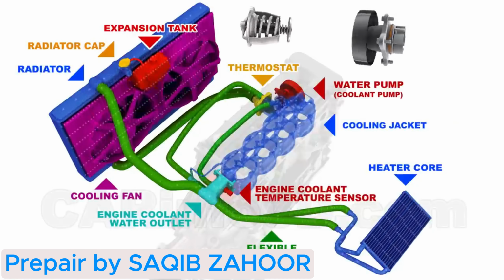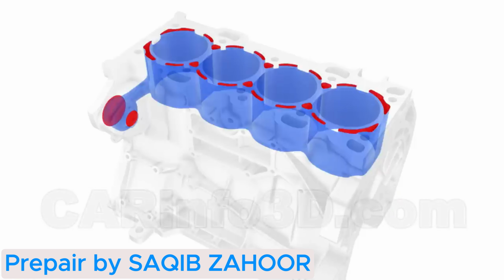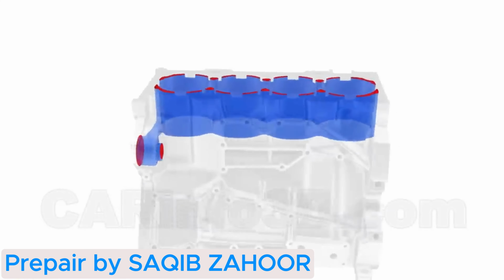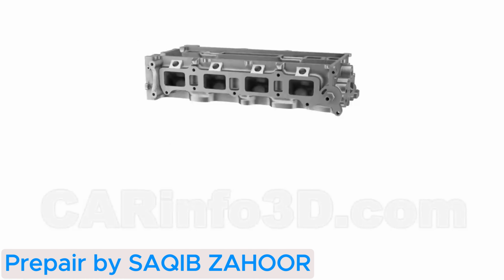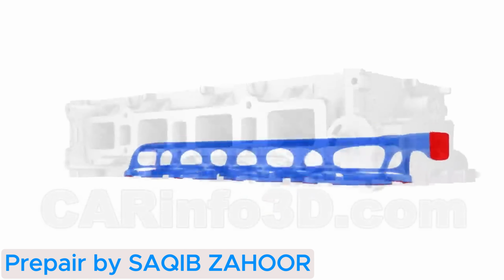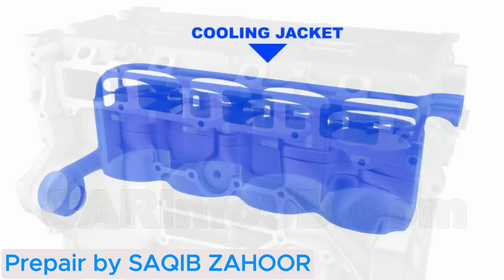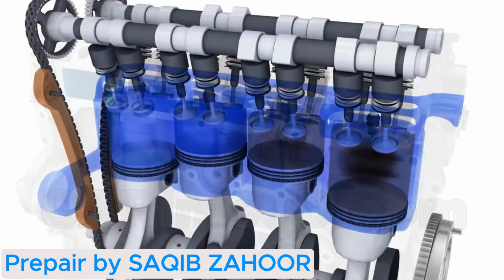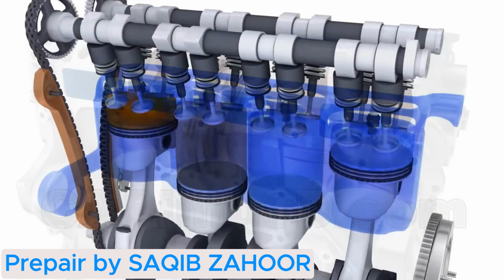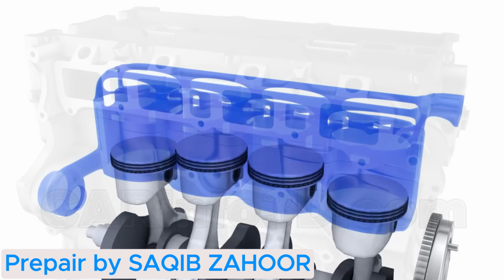Let's review the liquid cooling system in detail, via cylinder block ducts and cylinder head ducts. These ducts, known as the cooling jacket, are filled with coolant. The cooling jacket is situated around the engine cylinders and serves the primary purpose of removing heat from those cylinders.